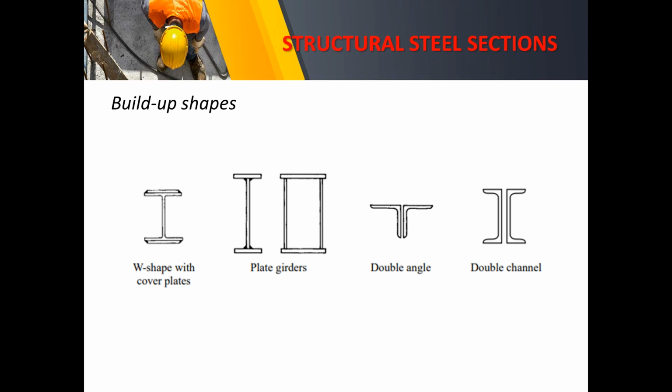They need to be combined with other shapes, okay, to increase their strength, of course, to increase also the moment of inertia that is essential in the design. Remember that the inertia is always present in your design formula, like the bending stress, that is MC all over I.